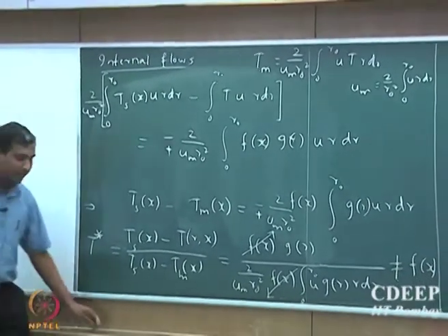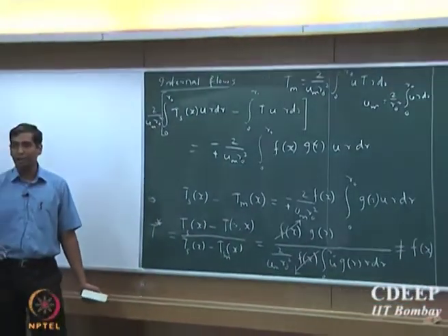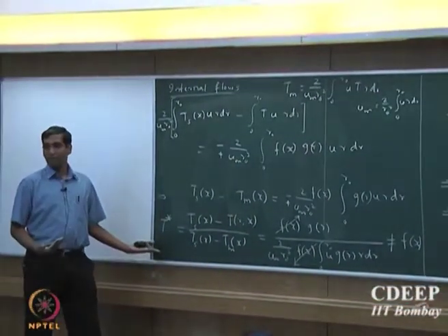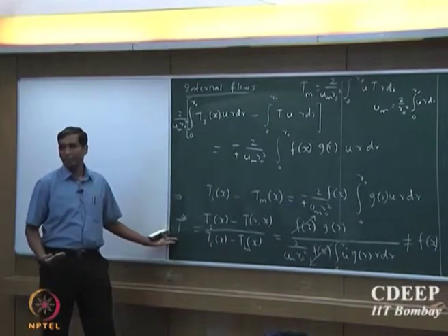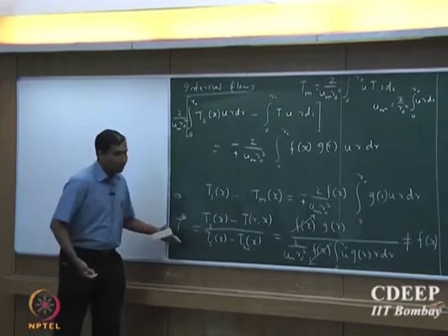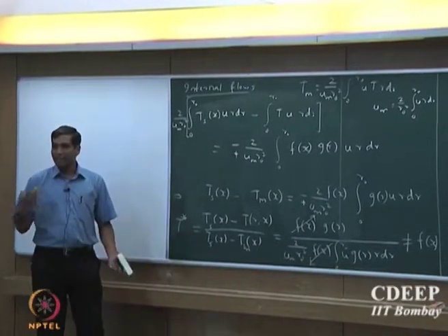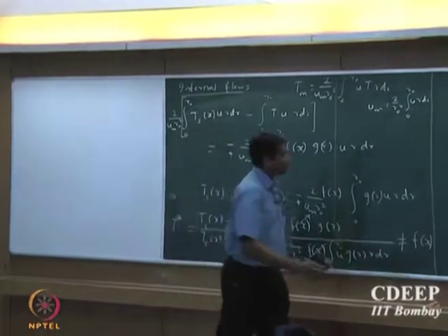This is a fundamental difference between the momentum boundary layer and the thermal boundary layer in the internal flow case. It's not the temperature profile which is not changing, it's the dimensionless temperature profile that doesn't change with the axial position. This observation can lead to some really interesting and intuitive results, which we will see in a short while.